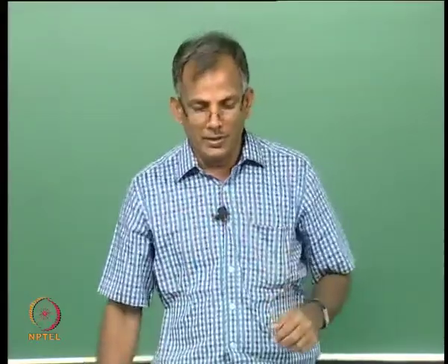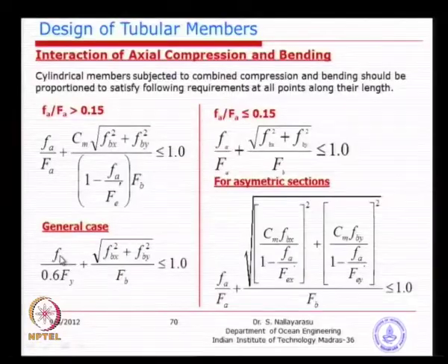That is why we compute the applied stress separately for axial, allowable stress separately for axial, and then applied stress and allowable stress for bending separately. Then we find the ratios and combine them, because we do not have a facility or an equation or experimental studies done for a combined allowable stress. You understand the idea behind why we are doing this now.